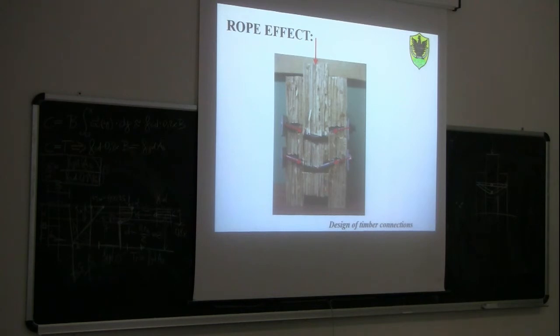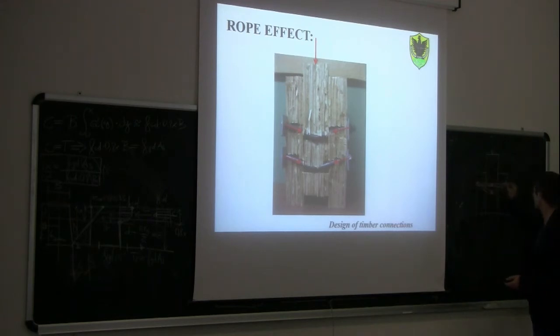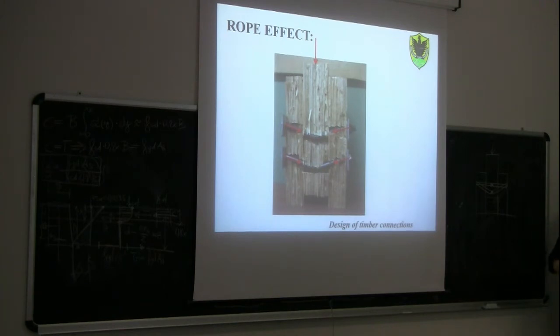Meaning that if this dowel is smooth, doesn't have any washer here, and doesn't have any thread inside, to stay in this configuration, like it was at the beginning, it should elongate quite a lot. So this is quite a significant elongation.